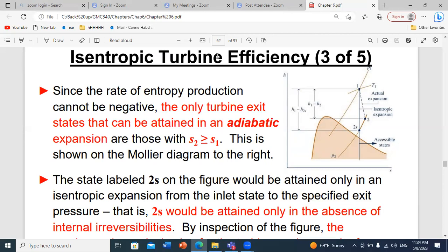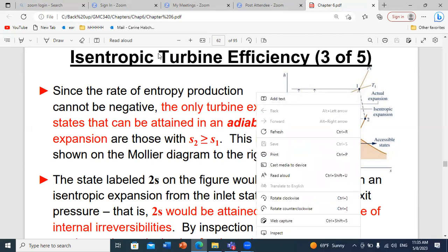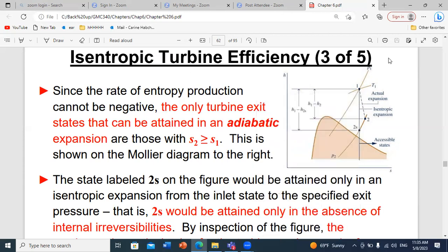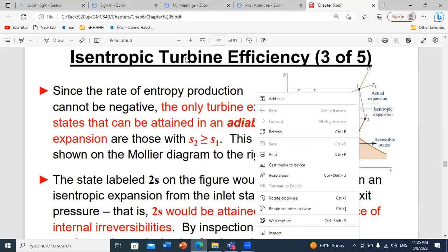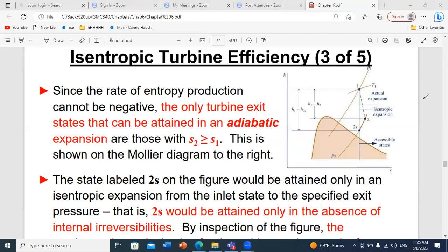We know this, but we can have this reduction in several ways. The first way is the isentropic process. Whenever you have an isentropic process, s is constant. So if I want to illustrate this process graphically, I go from 1 to 2 with constant s, while h will decrease. So this is point 1, this is point 2. As you can see, h is decreasing, but here it's decreasing straightforward with s constant.